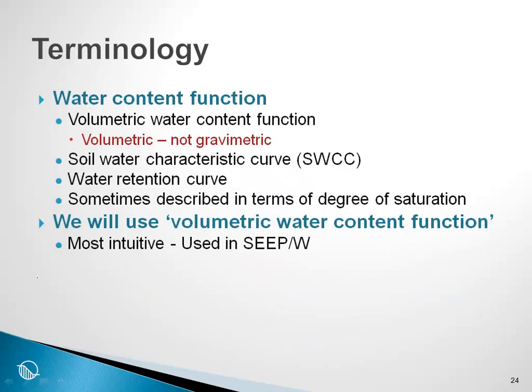Let's talk a little bit about terminology. The water content function, notice that it is volumetric. It is not gravimetric. And you will find in the literature that many people use the terminology soil water characteristic curve. Soil scientists tend to use water retention curve. Sometimes the curve is presented in terms of degree of saturation instead of volumetric water content.